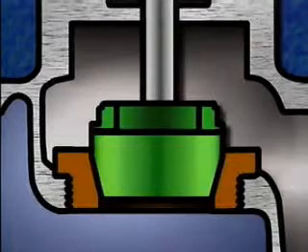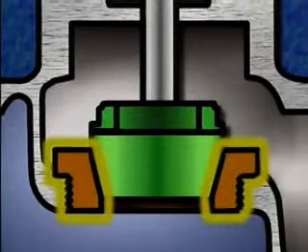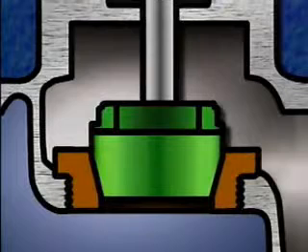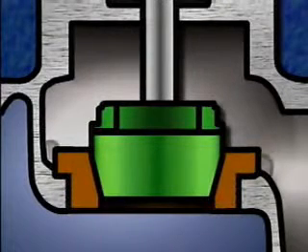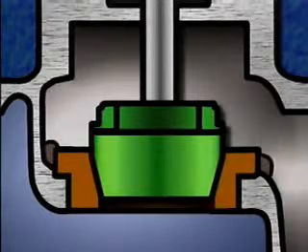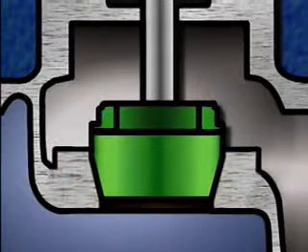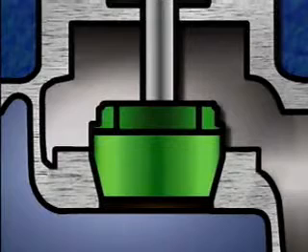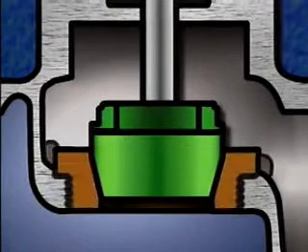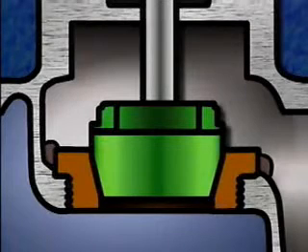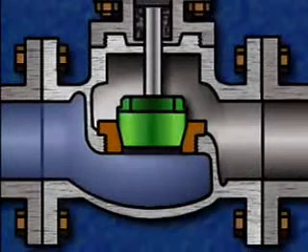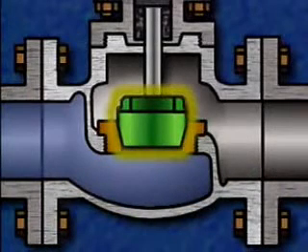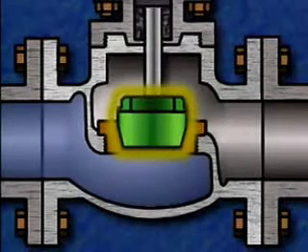One of the internal components is the valve seat. The seat is a stationary component of the valve, and it can be threaded, press fit, or welded into the body of the valve. In some cases, the seat is cast as a component of the valve body. In high-pressure, high-temperature situations, the seat may be both threaded and welded to prevent leaks. The seat is used together with a movable component called a disc to control flow through the valve.